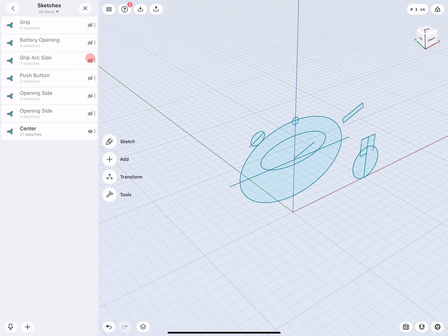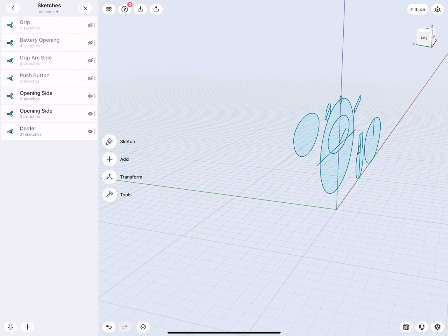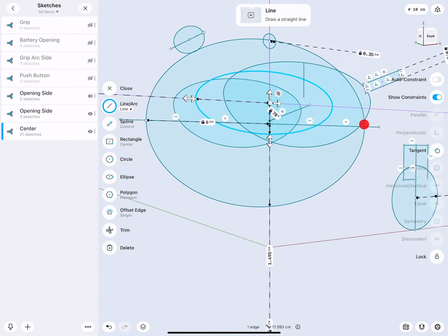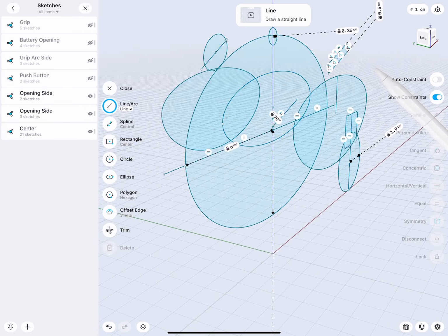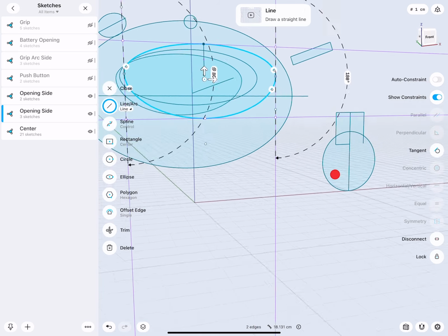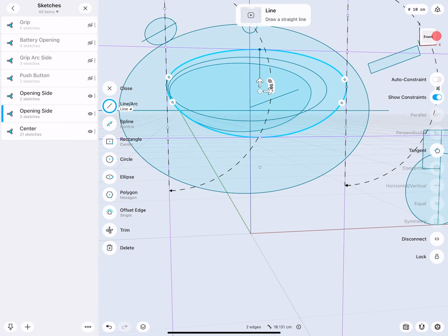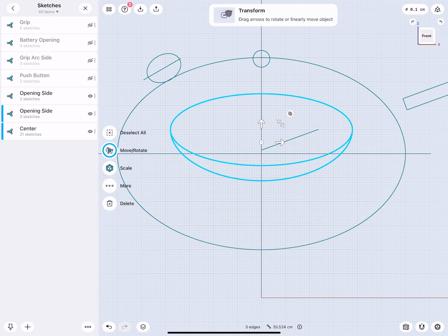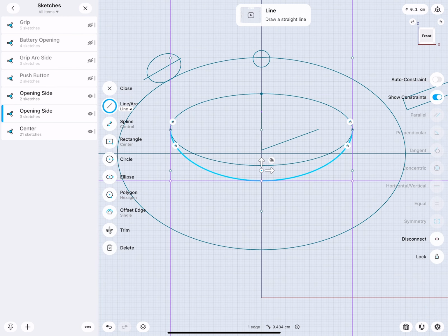Now, going back to here. The next logical step is to work on the opening. I have an ellipse here at the center. And then I have a sketch left and right where I have 50% of the upper ellipse. And then I put in a CV curve. So this way, as you can see, the upper area of my second sketch maintains the profile of my initial ellipse, but at the bottom, it has a different shape.